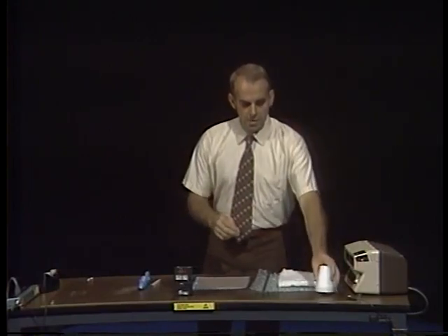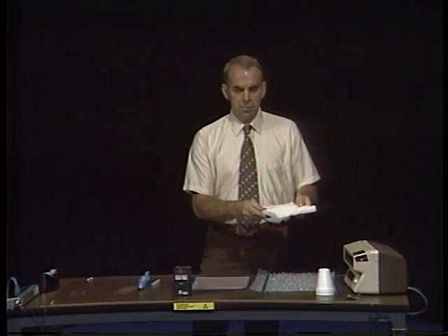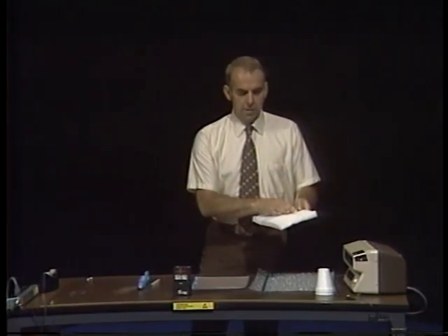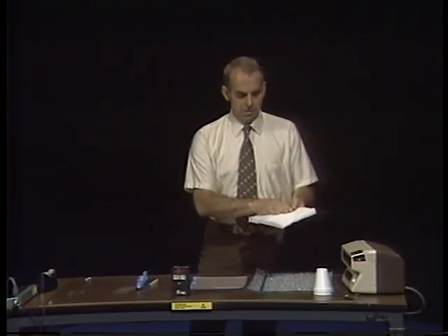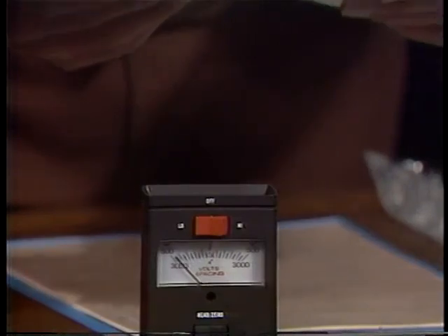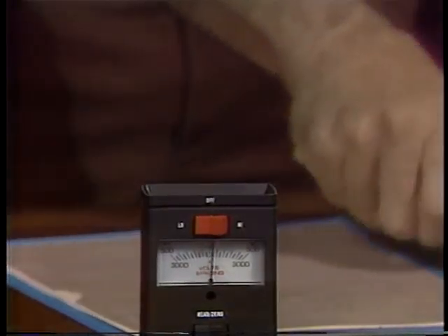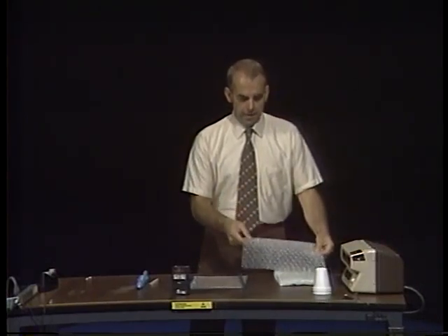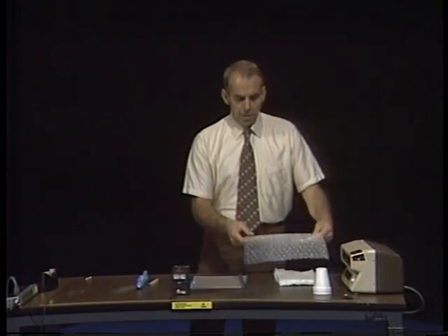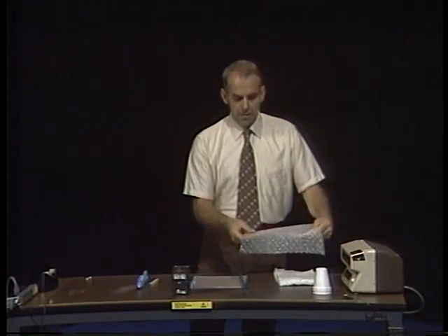A similar material is this white padding foam, which is often used to wrap electronic subassemblies. This material, too, is a high static generator, particularly when it's been rubbed or handled. More than enough to pin the meter. The third offender is ordinary transparent bubble pack, which becomes highly charged with handling or with vibration and friction.